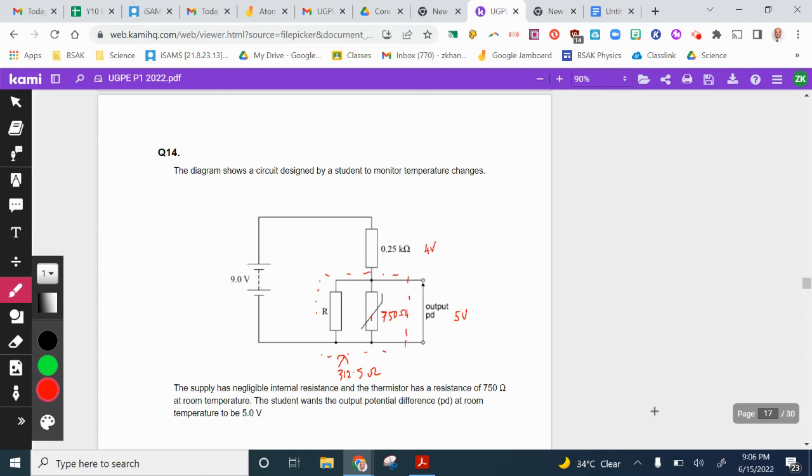Knowing the current here, using resistance equals voltage over current rearranged, we can work that. And knowing the current here using the same technique, we can then find the current that we should get across the resistance here. Okay, so we know that the current here minus the current here will give us the current there. We know now the current through here. We know the voltage is 5 volts, and with the voltage and the current, we can work out the resistance here.